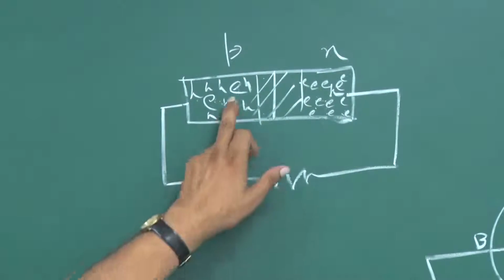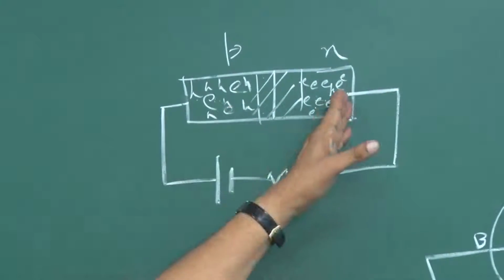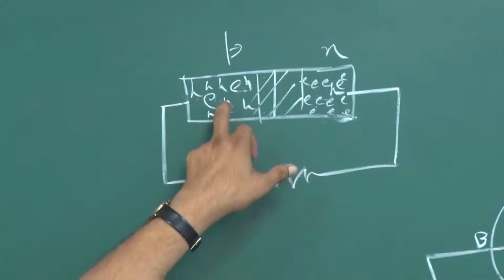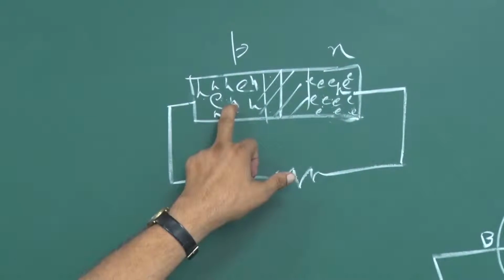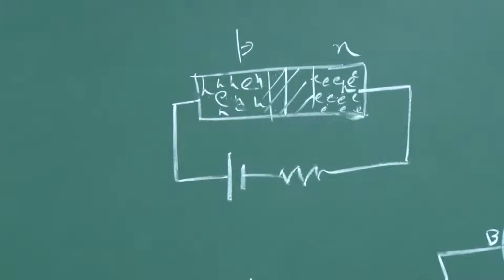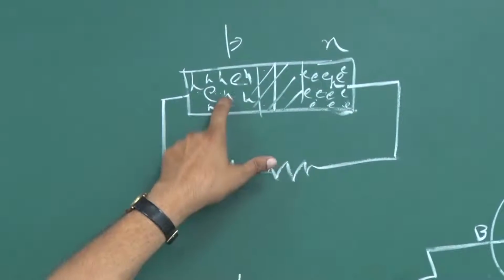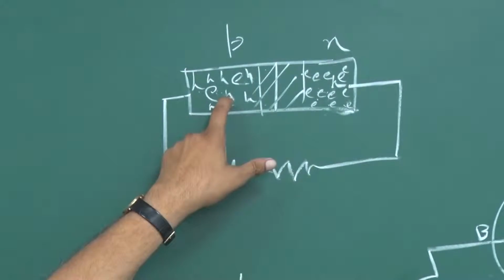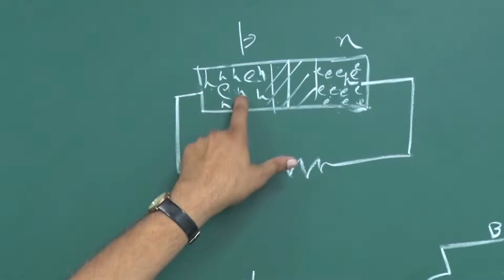And if an electron hole pair combines, the electron is coming from here, but the hole which was there for all that charge distribution, charge neutrality, electric field, potential, this battery will maintain all those things as a function of time. So, if this hole is filled, a new hole should be created somewhere to maintain that charge balance.